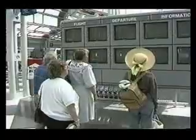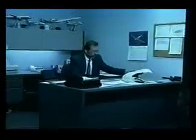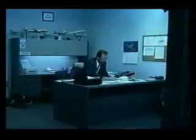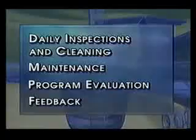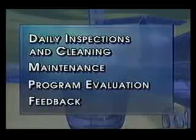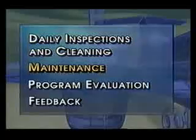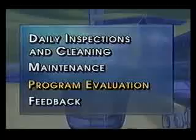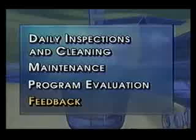In a perfect world, corrosion control would be easy, with an unlimited budget and unlimited time for maintenance. But in the real world, limited resources require you to analyze your maintenance needs and determine when and how effective corrosion prevention techniques can be employed. From this point, we recommend you institute corrosion control into the following 4 elements: daily inspection and cleaning, scheduled and non-scheduled maintenance, evaluation of program effectiveness, and feedback to FAA, manufacturers, and fellow operators.